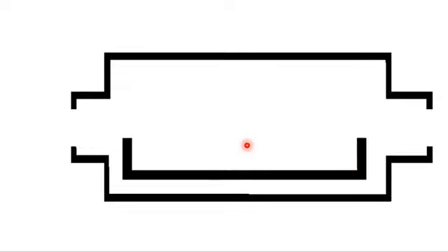If the melting point of the sample holder is less than the melting point of the sample present inside the holder, then this will cause incorporation of impurities from the sample holder into the sample or precursor. So this is the main reason that the melting temperature of the precursor holder must be very high as compared to the source material.